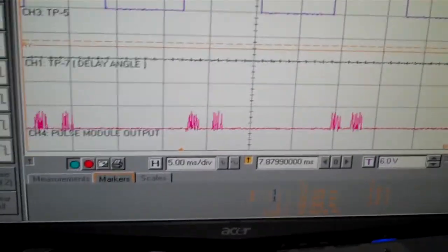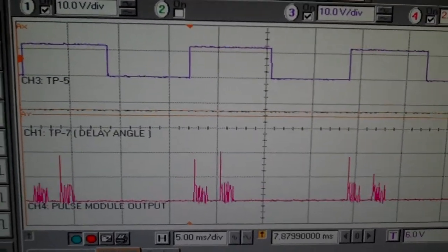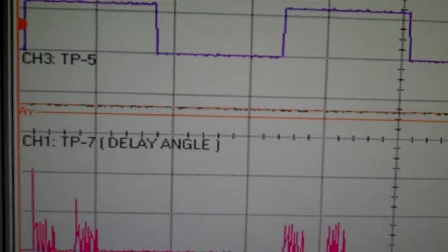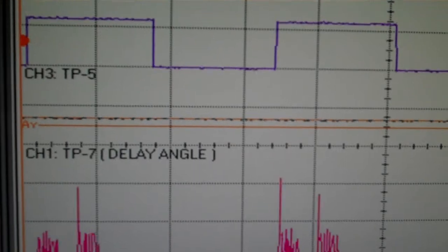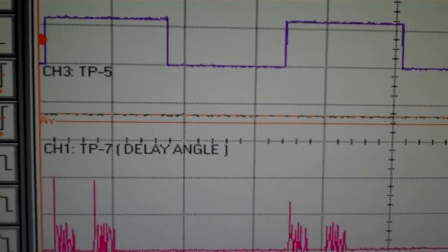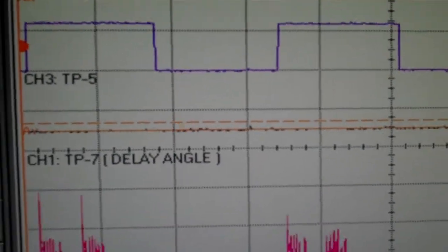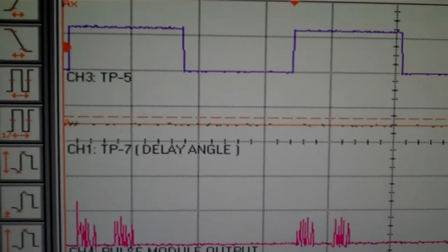So first we're going to go to U6 pin 7, and that will be the upper threshold. We can see that it's already marked with the first marker. Then that's the 7 volts, and we're going to go to U6 position 4. That's the lower threshold. That's approximately 5 volts. Now that's basically checking.